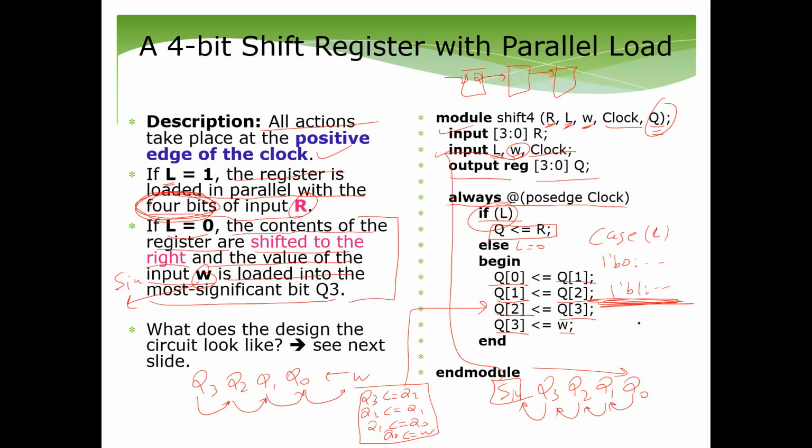I remember one of the questions in the homework we had a register that will do four operations. I don't quite remember what the operations were, but there was hold, shift right, shift left, and parallel load. So make sure you have signals for all of that. You need 2 bits selection, and using a case statement you can have these 4 combinations.